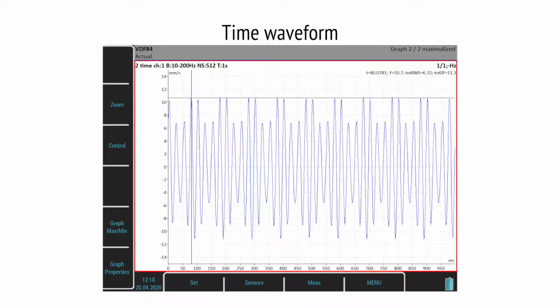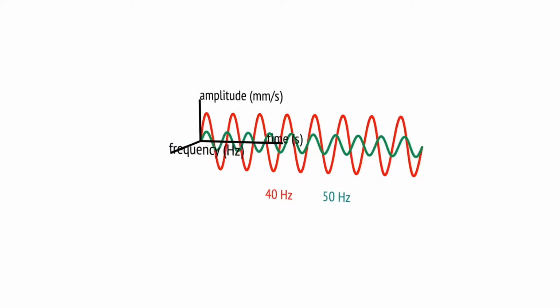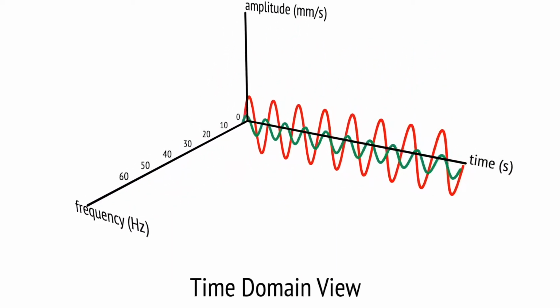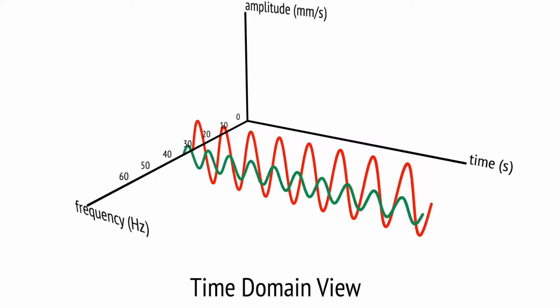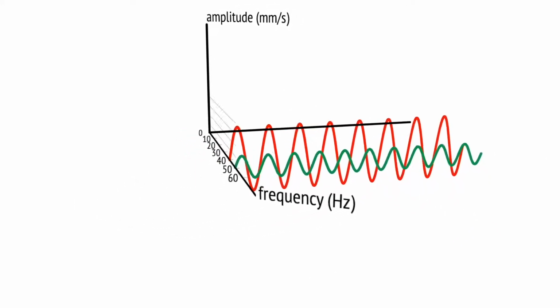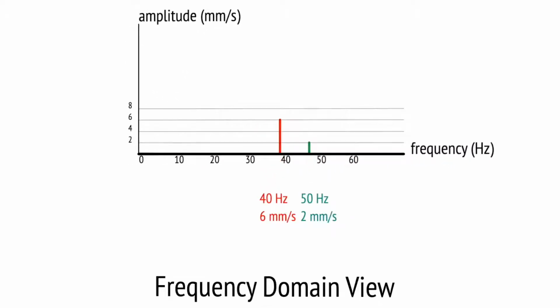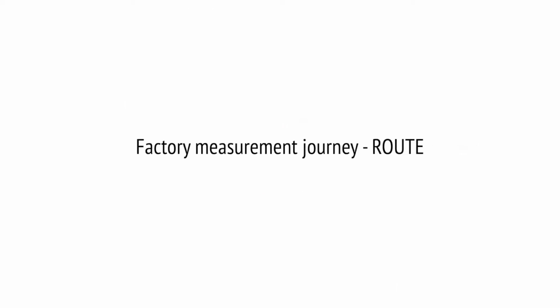Finally, you choose the spectrum view on a measured signal, so the signal will be decomposed into discrete frequencies and shown to you from this view. And from this point of view, you can easily say that the motor with the speed of 40 Hz is causing the problem.